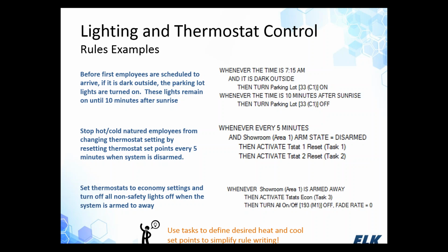Now, we're actually doing that a little bit differently using a task. If you see here, the "then activate thermostat task." A task is a small subroutine. Instead of us rewriting all these, I want to set the cooling temperature to be this, I want to set the heating thermostat to be this, and constantly rewriting that, we're just associating that along with a task. And we have a lot of those tasks. You can find them on our website and also in previous webinars that we've done in RP software.